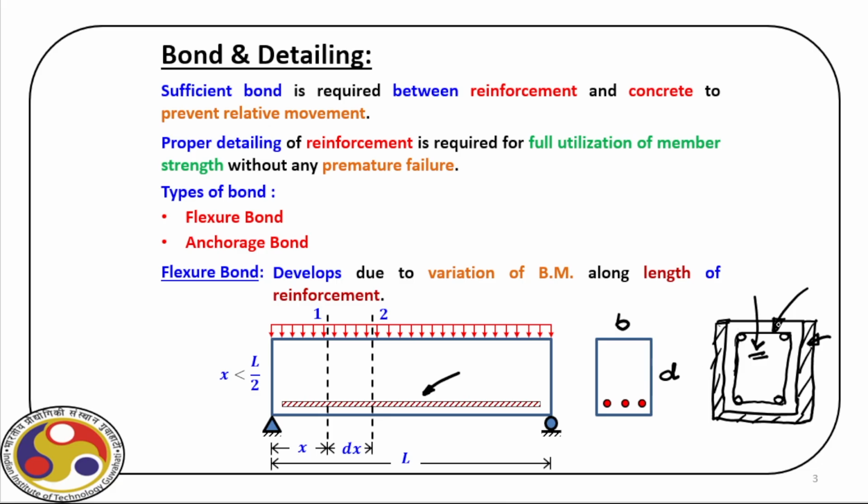Now once we get this rectangular beam after removing the shuttering and then apply the load, as you can see here, then this concrete and the rebars inside the concrete should behave monolithically. And that's the reason we should have sufficient bond between the reinforcement and the concrete, so that there is no relative deformation. So if this is a beam spanning over simple supports, the moment we apply a load here, it will start bending like this.